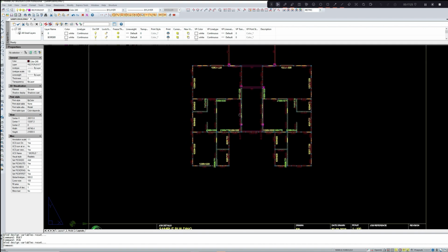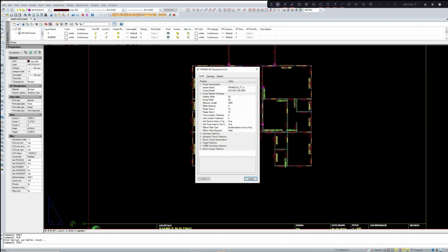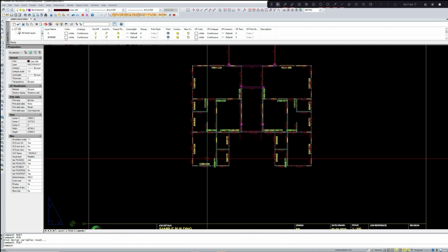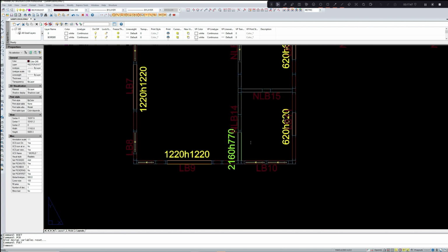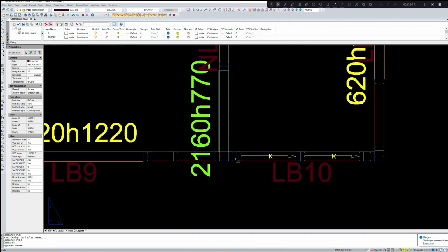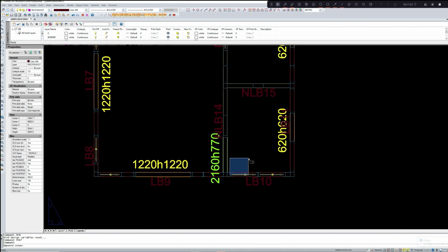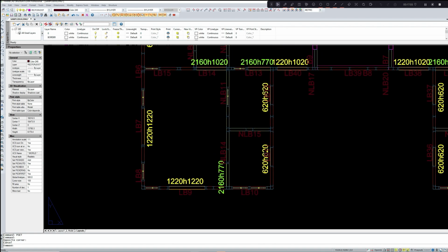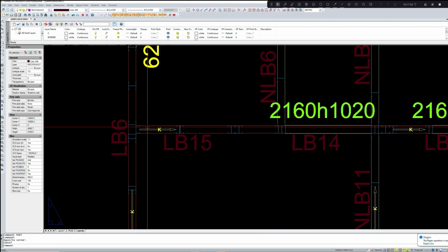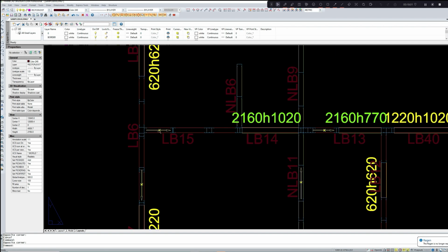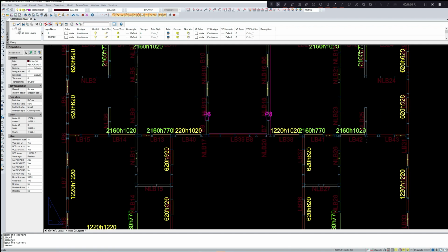Now let us look for the position of strap bracing. For that we have to go to P set, base panel, so change it here, strap braces, double strap shape. So let us try to insert a brace here. It is not possible, so let us try to insert a brace here. This is also not taking a brace.